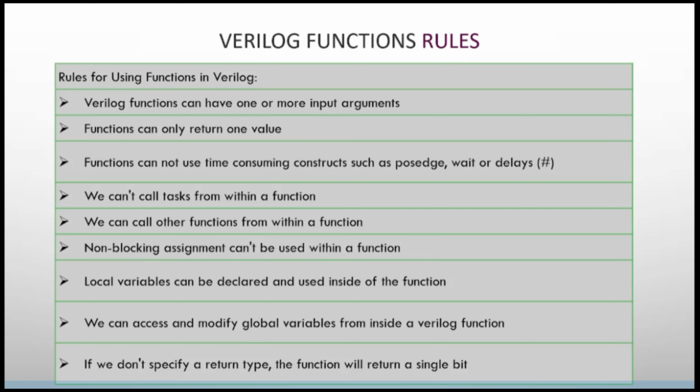Now coming to Verilog function rules. While you are defining a function, you should follow certain rules before defining any function, which are sometimes considered as advantages and sometimes as disadvantages while using functions. The first thing is, Verilog functions can have one or more input arguments, and functions can only return one value. When you are writing functions, they can only return one value at a time.